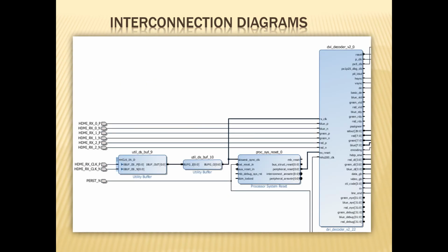Some interconnection diagrams on larger, more complex systems with multiple electronics or components can actually span multiple pages. They're still giving us a reference between components, and they're still showing us what our pinouts are going to be. But now we'd have to use a page reference in order to find what the complete system is going to look like.